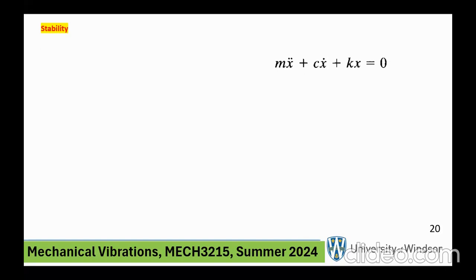Now, when we solve this, if there is no damping, this is going to be strictly oscillating forever. If there is damping, such as what we have here, viscous damping, the oscillation amplitude is going to die down. And eventually, after infinite passage of time, it will reach zero. So essentially, it will never go to zero, it approaches zero.